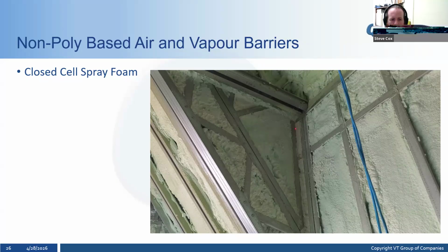Really, a pre-drywall blower door test is highly recommended in my mind anywhere we have a spray foam assembly, especially if there's an unvented attic. So an unvented attic, I mean, if there's a flat roof or a cathedral ceiling where the spray foam is the insulation and the air barrier all in one.